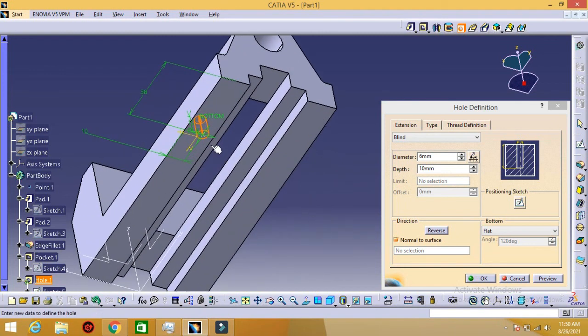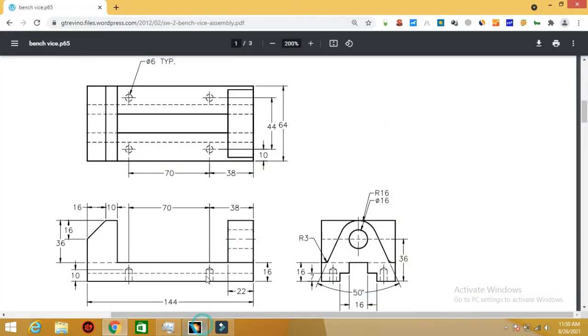I made one hole. Okay, but there is another thing. What do you see in this diagram? You see a pointed piece. This hole is not flat. See this point. Here also you see this cone shape. This shape comes when you use a drill bit. You get a V bottom. It's not a flat bottom. A flat bottom would have been if these two lines would not have been there.